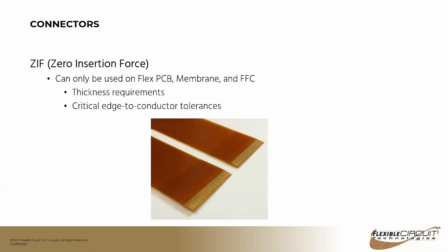ZIF connectors are probably the most common way to terminate and connect from a flex circuit to either another flex circuit or possibly a rigid PCB. These are typically only used on flex PCBs, membrane switches, or flat flexible cables. There is a very strict thickness requirement that is recommended, as well as critical edge to conductor tolerances. So these would all be specified on the connector manufacturer's print, and we're very well versed in it. I would say 70, 80% of the designs we see have a ZIF connector incorporated in them.